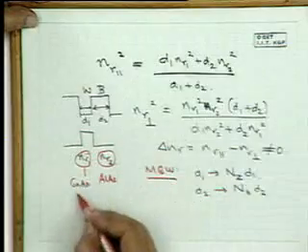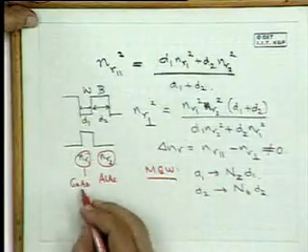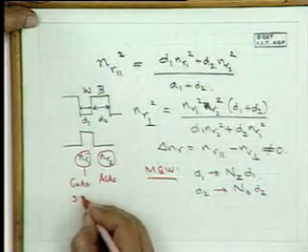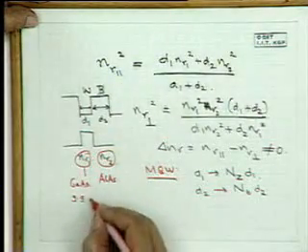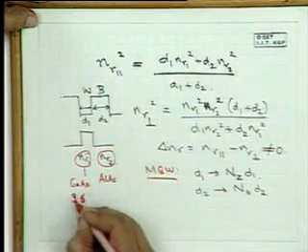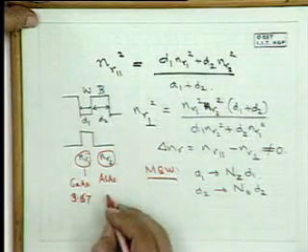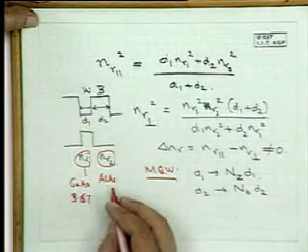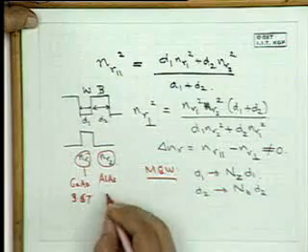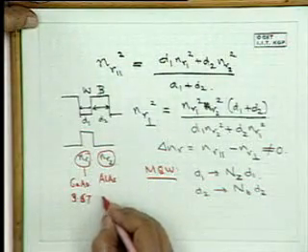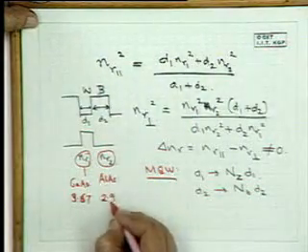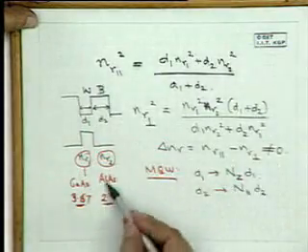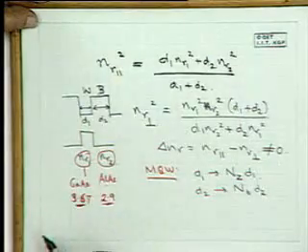Remember, gallium arsenide, what is the refractive index? It's typically something like 3.3, 3.67. And aluminum arsenide? Aluminum arsenide is less. It's about 2.7 to 2.9, about 2.9. So there's quite a lot of difference. Aluminum arsenide has to be less.